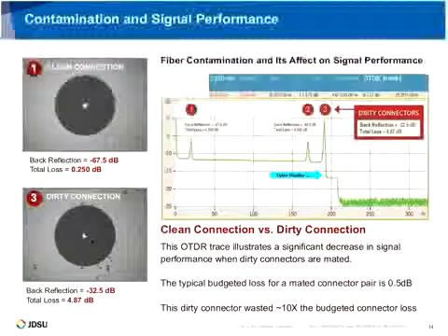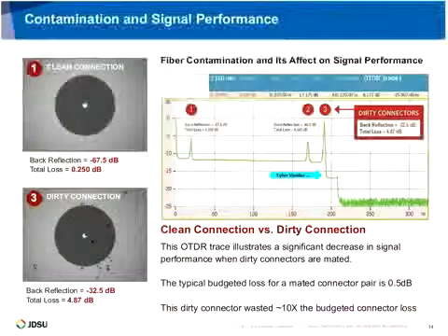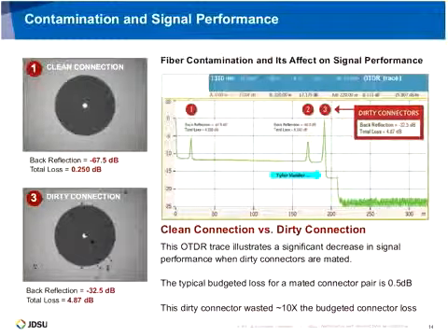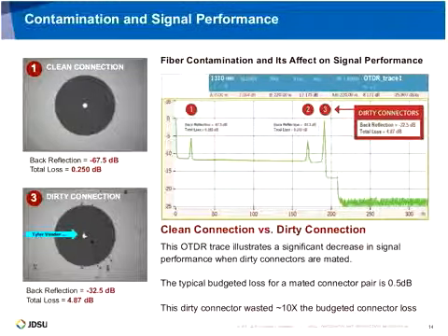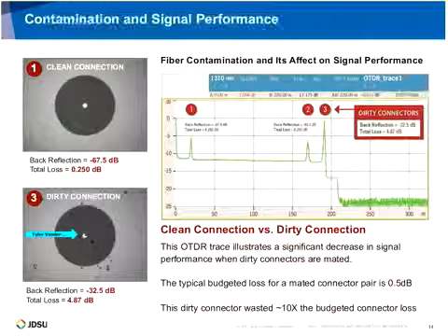And so now I included a screenshot of what one of those fiber interfaces looks like, and you can see here it's a dirty connector. There are little fragments of contamination here or there, but I particularly want to highlight, if you can see at the core of the fiber there, at around the 2 o'clock area, there's a small particle that's partially blocking the core of the ferrule there, of the fiber, and that's likely the cause of that 5 dB loss.